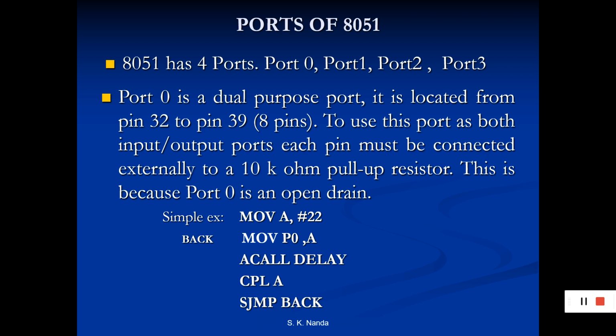8051 has 4 important ports, namely port 0, port 1, port 2 and port 3. These ports allow microcontroller to connect with the outside world. The 4 ports of 8051 microcontrollers have certain specific functions and corresponding features also. Port 0 is characterized by 2 functions. First of all, it is located from pin number 32 to pin number 39 in all 8 pins. To use this port as both input-output port, each pin must be connected externally to 10 kilo ohm pull-up resistor.